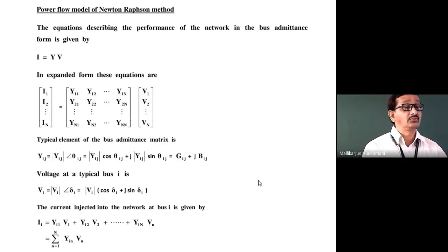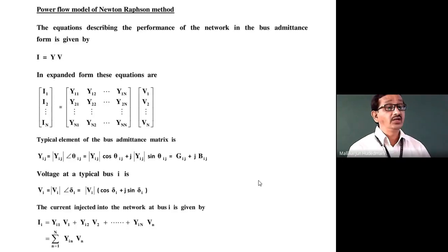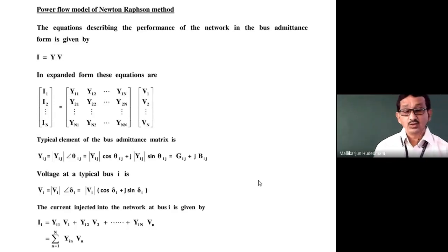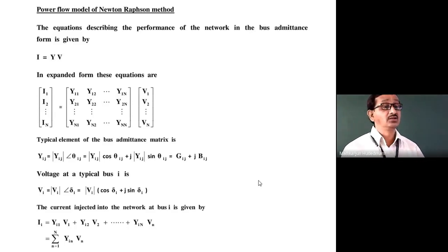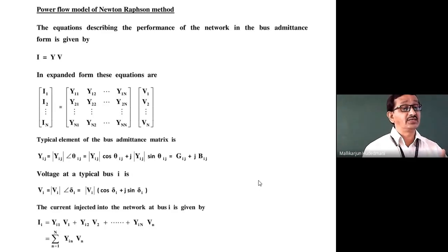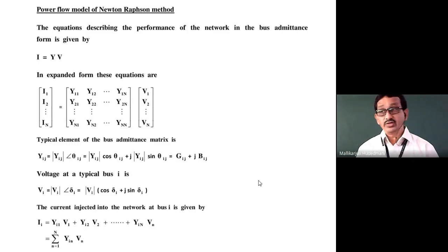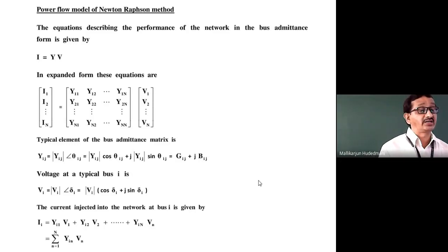And the last term, Y into V, V is what? Bus voltage. If you have n buses in the system, voltage at bus 1, bus 2, bus 3, bus 4, the transmission ports where incomer and outgoing terms and load drawal occur. We call them the terminations where exchange of power takes place. So for those bus voltages, if I say n, you will get a column vector V1, V2, V3 and Vn like that.